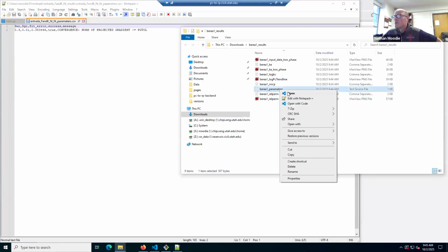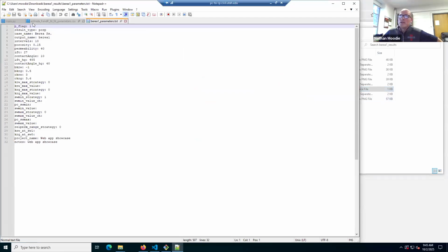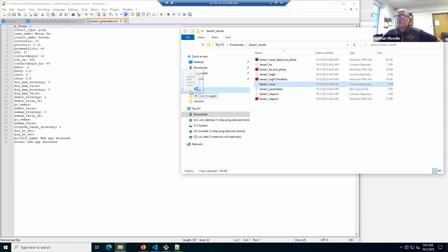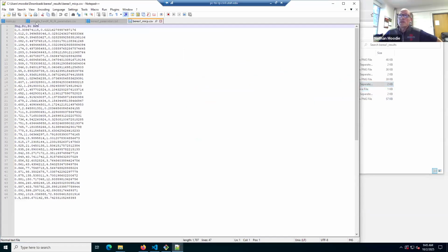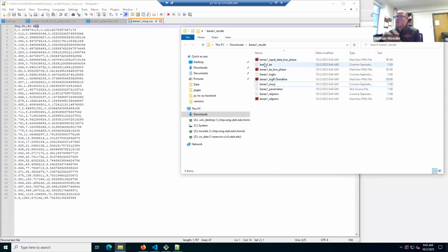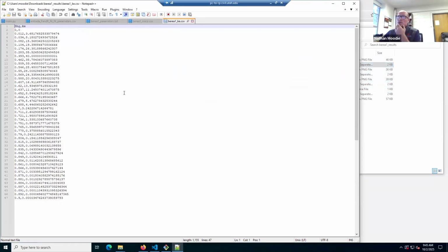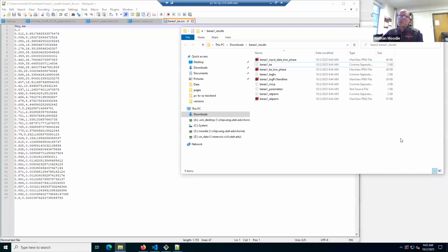As well, now you have your parameters file here. These are the parameters that went into the method. To show you those, this is the input data, the MICP data, your saturation of mercury, capillary pressure of your test data, as well as the converted capillary pressure of your reservoir here. As well, it output the charts that we were looking at. This is your effective permeability calculation. So it outputs all the data so you can go back and check and make sure that it all makes sense. There aren't any problems.